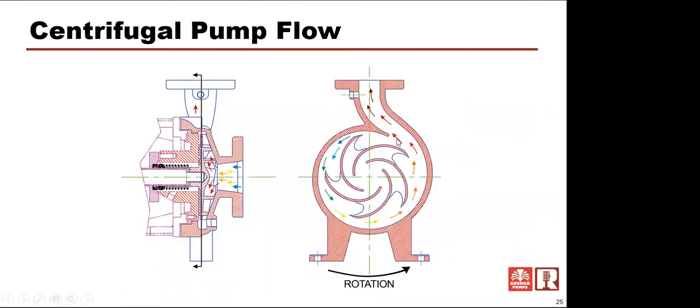So when we look at a centrifugal pump, this is normal. It starts building pressure as this flow starts coming around this casing of the loop and coming over here where it really reaches its largest pressure rating, typically on the discharge side.